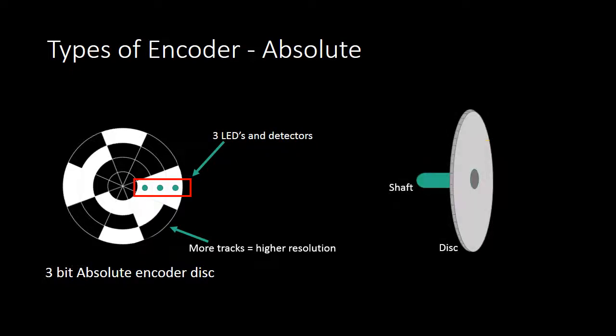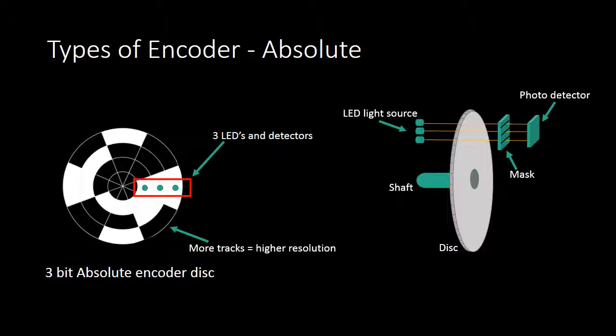An optical encoder may have a mask installed between the detector and the disc, which increases accuracy by sharpening the edges of the light pulses falling on the detectors. The mask also allows for adjustment to discs of different resolutions, but can also increase cost, has a risk of interference, and allows less light to the detector. Optical encoders increasingly use no mask in favour of better technology in LEDs, detectors, and lenses to reduce phase error and increase edge detection.